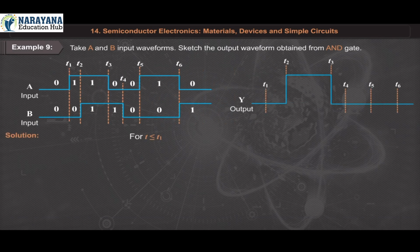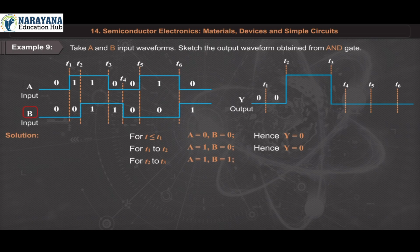Solution. For t <= t1, A = 0, B = 0. Hence, Y = 0. For t1 to t2, A = 1, B = 0. Hence, Y = 0. For t2 to t3, A = 1, B = 1. Hence, Y = 1. For t3 to t4, A = 0, B = 1. Hence, Y = 0.